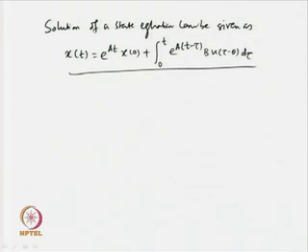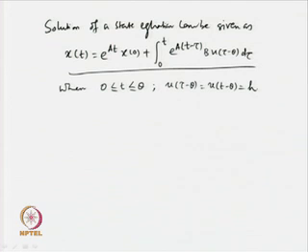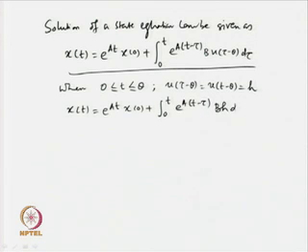How can we use the state solution for the state equation for our case? When we consider the time range t between 0 to θ, during that the input u(τ - θ) = u(t - θ) is h. Then the state equation can be written as x(t) = e^(at) x(0) + integration from 0 to t of e^(a(t - τ)) b h dτ.